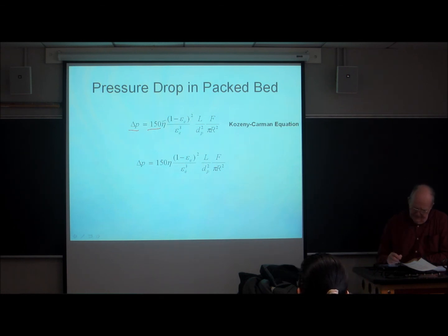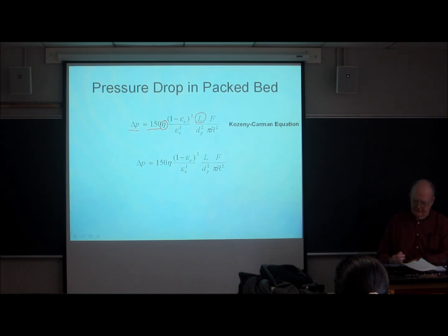The pressure is proportional to the viscosity. Certainly you know by now that the viscosity of liquids is way higher than viscosity of gases. I mean, gases were hundreds of micropoise, liquids were fractions or hundreds of millipoise or a few centipoise at most. Proportional to the viscosity, proportional to the length of the column to the first power, proportional to the flow rate to the first power under laminar flow conditions.